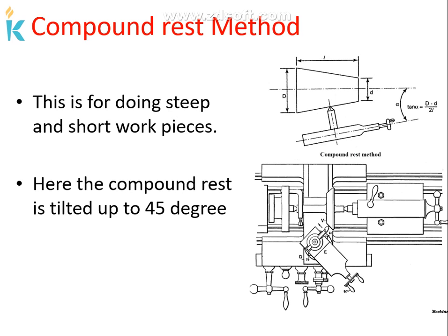In the compound rest method, this is the diagram shown in the presentation. In this diagram, tan alpha is equal to (D minus d) divided by 2L. So alpha is the half taper angle. In this method, we can produce up to 45-degree taper.